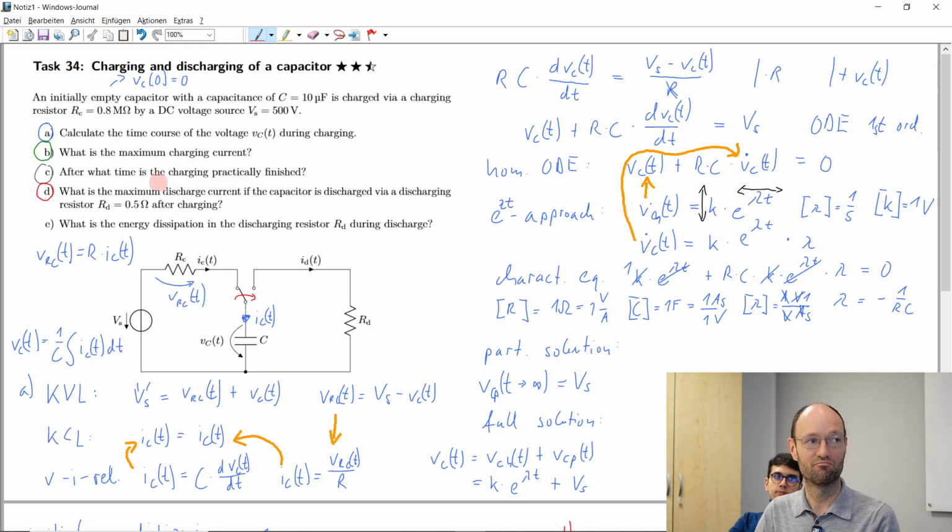So you take a 12 volt source, and the 12 volt would not be sufficient to do any harm to the animals. So with the 12 volt you charge some inductor, and then every 2 seconds or so you discharge this inductor over some much larger resistance, and then you get voltages in the kilovolt range, and this will be not really dangerous, but they cause some pain.